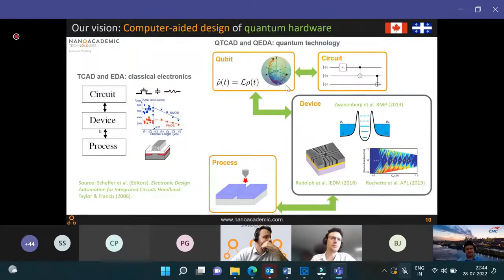And then this 3D structure can be input into a device simulator, such as, for example, Sentaurus Device, or equivalent Cadence, or equivalent TCAD products, and calculate, for example, current-voltage curves for individual or few transistors based on physical models. And then once those performances of few devices are obtained, it's possible to input them in the circuit simulator in which compact models of transistors are used, enabling us to solve for chips containing millions of components. So this is actually an integral part of the electronics engineer's workflow used every day by the industry.